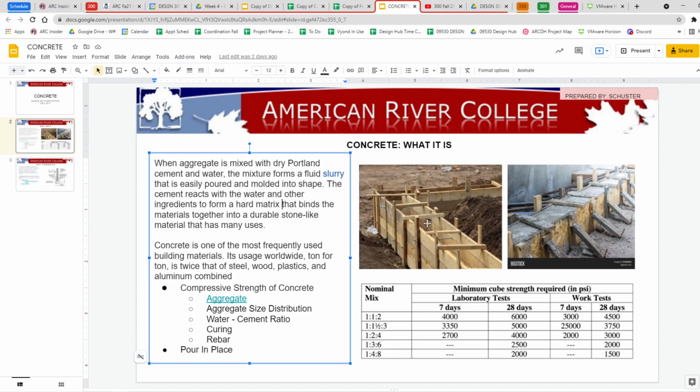Now, so you pour it in here. I mean, we don't do this around here. We don't have this kind of wood to be able to form like this. We form a combination of this. These little ties hold these things together. You pour that concrete in there and it wants to shove everything apart. And of course, as you get taller and taller and taller, there's more load. So usually there are tie bars in between. But here there's no tie bars. You just brace it. That's often done too.